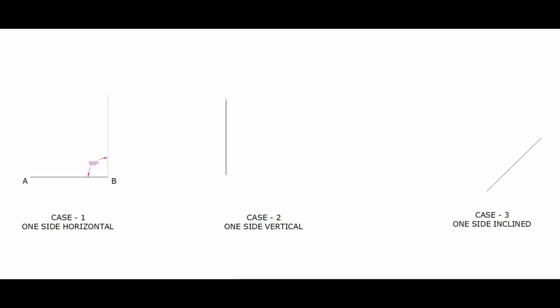A perpendicular line can be drawn with the help of a protractor by taking 90 degrees from the endpoint of the line. Measure the distance of the side in the compass and mark it on this perpendicular drawn from the endpoint and name it as C. This line BC is the second side of the square.